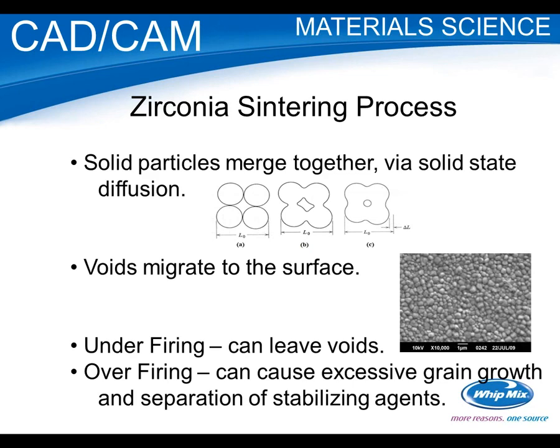That really isn't the case with zirconia. It's really not melting. You have a couple of grades. You've got one grade for copings, which is very opaque, and people don't try to overfire that. But the other grade is for translucency. They want to get the translucency of porcelain, and to be honest, it just doesn't happen with zirconia. Zirconia isn't that translucent.